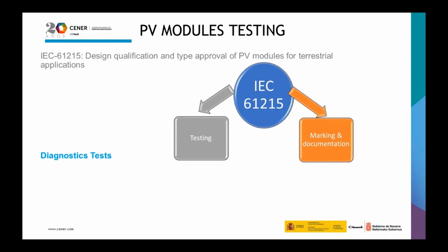The philosophy of the standard for testing is: first, initially some diagnostic tests are performed, then the modules are subjected to some ageing tests, and the diagnostic tests are repeated to see the degradation that the module has suffered. There are also some characterization tests, and then a pass or fail criteria is applied.